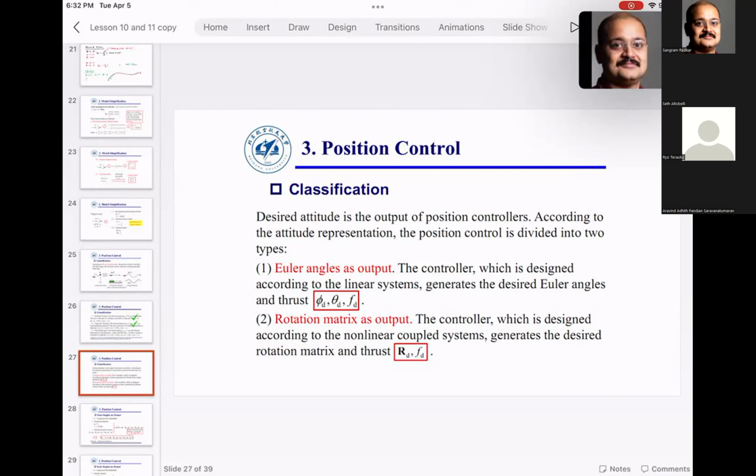Nothing is wrong with the algorithm, but the altitude and attitudes that you estimate based on these angles are not going to be accurate. That's why you would have to use either quaternions or rotation matrices. MATLAB can do both. As a matter of fact, you can implement the quaternion-based implementation inside Mambo, and Tello already implements the quaternion-based implementation.